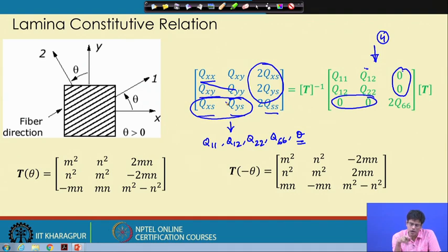This is what I wanted to share with you for the lamina constitutive relation, which you will probably learn in more detail when you study composite technology or composite mechanics, where how to find the constitutive equation for a laminate will also be discussed. A laminate is essentially several laminae placed symmetrically or antisymmetrically, and through thickness integration we can obtain the constitutive behavior of the laminate. So, this actually completes our